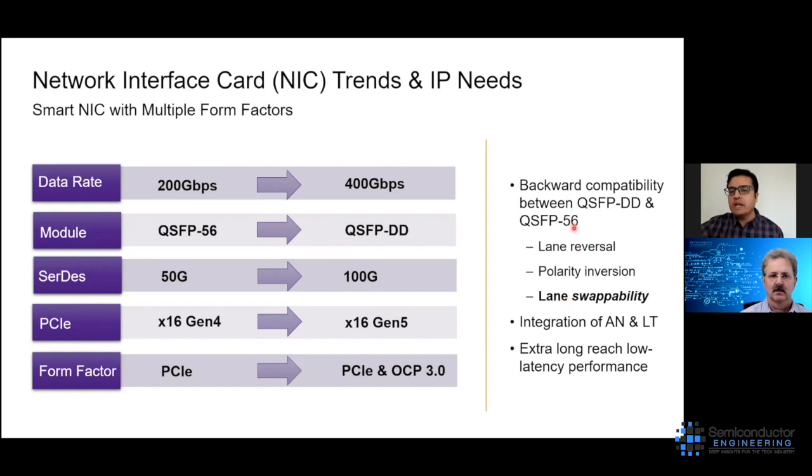So these put very complicated requirements on the design of SerDes. When you design a macro, you need to ensure all these features can be supported so that this NIC can support backward compatibility between QSFP56, QSFP-DD, and OSFP.